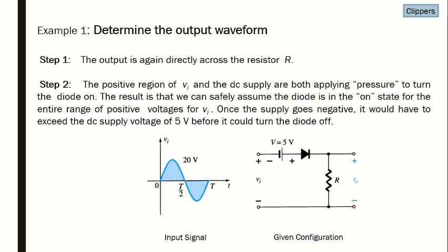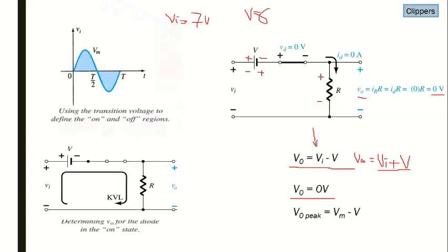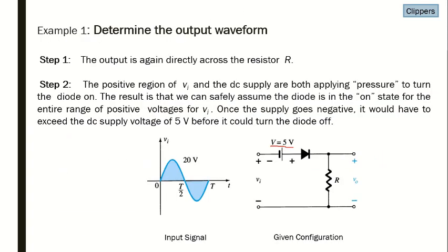Now this is what we just discussed, that the battery potentials are opposite. Here the battery potentials are plus minus, here the battery potentials are minus plus. So it seems that whatever the input voltage is, we'll be getting a positive 5 at the output V naught. So Vi is equal to 0, we'll get positive 5. When Vi is equal to 1, we'll get 1 plus 5 is equal to 6. So let's see what we can possibly do.